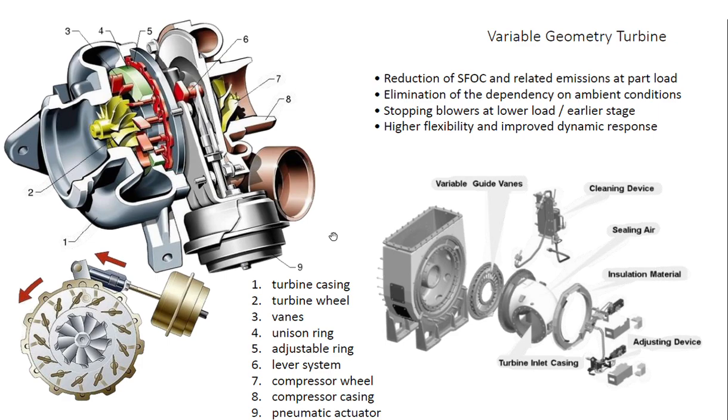Now VGT, that is variable geometry turbocharging. When we talk about variable geometry, it has a reduction in SFOC, specific fuel oil consumption. It also eliminates dependency on ambient conditions. We also have stopping of blowers at an earlier stage at lower load, higher flexibility and improved dynamic response. So dynamic response also gets improved.